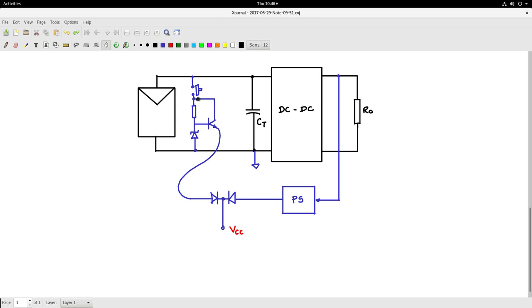So all you need is for this to be on for just a few milliseconds, so that there is enough number of high frequency carrier cycles that will build up the voltage for the DC-DC converter. Actually when you press and leave it, the human reaction time itself is around 10 milliseconds. There is more than sufficient number of high frequency cycles possible for the DC-DC converter to build up the voltage, which will then start self-sustaining itself. So this is the startup circuit that one may use, because you are just using it for a fraction of time with a very small duty cycle.